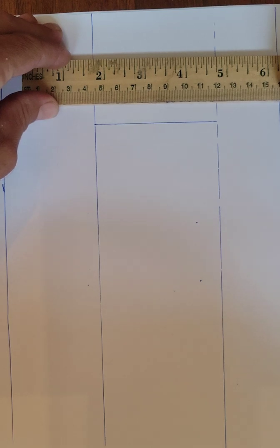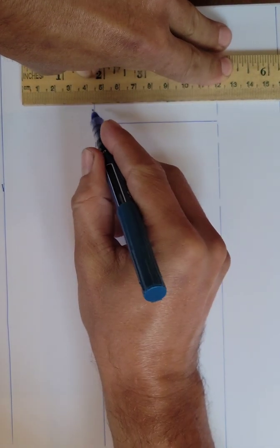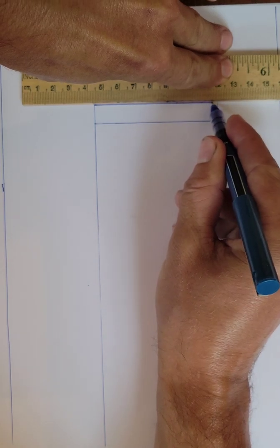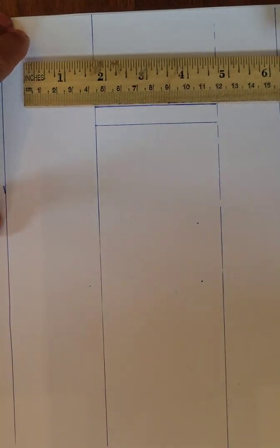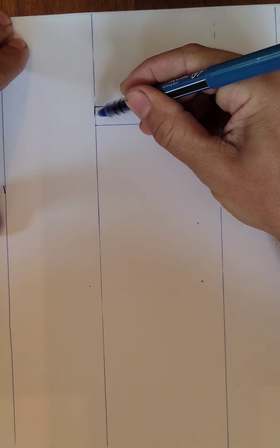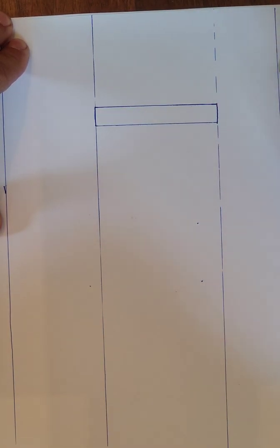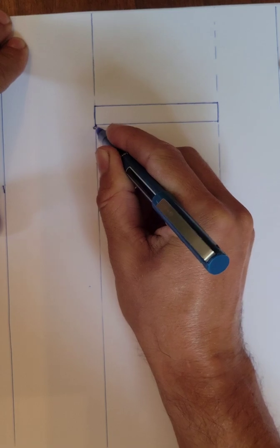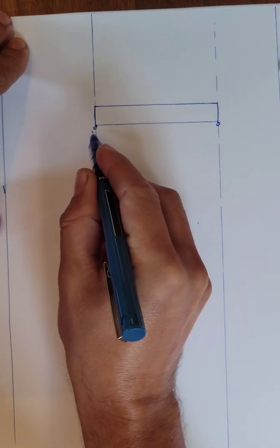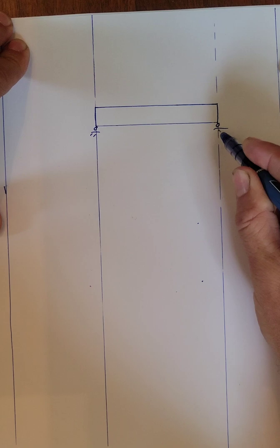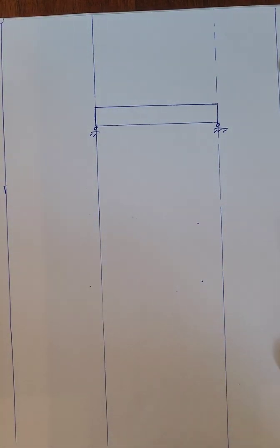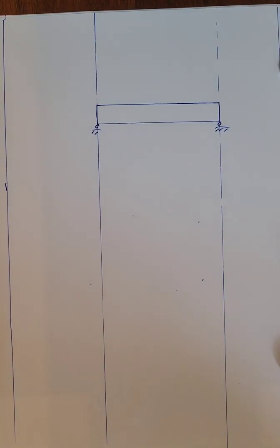One thing that I'll challenge you guys to go out and do is take a look at the support structures on the ends of bridges, right? And you'll notice that there are these large steel dowels that the bridge is supported by. The purpose of that is to act as a pin joint, meaning that we won't generate moment on the ends.